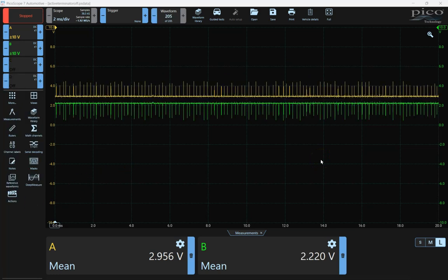So in this case, I removed the active terminator, same machine, and I only had the passive terminator in place. That so-called passive terminator would not have any power, because the active was not connected, it didn't have any power.